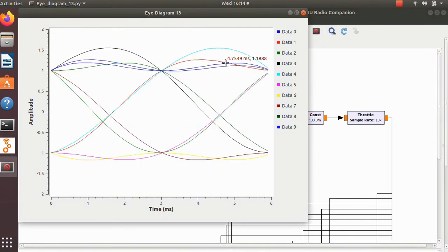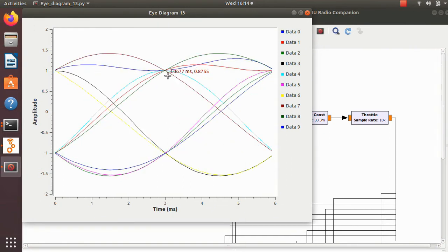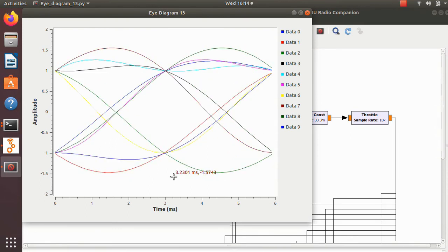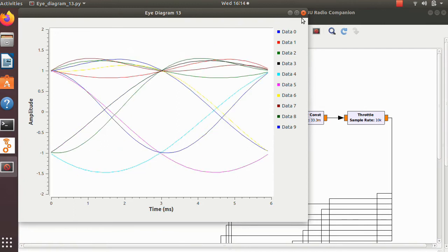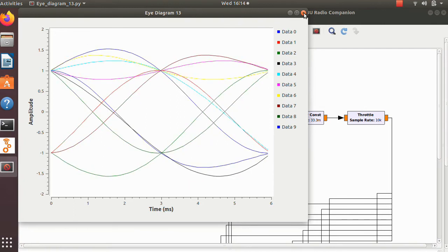we can see what we were expecting to see. A raised cosine does not have intersymbol interference, so we see the bit transitions very clearly in this eye diagram, which was what we anticipated by putting two RRCs in series with each other.